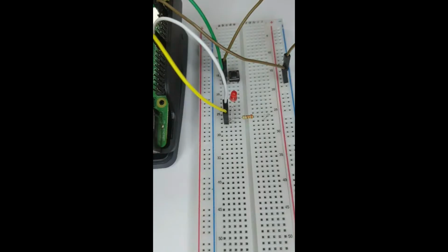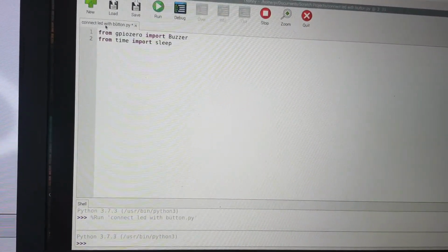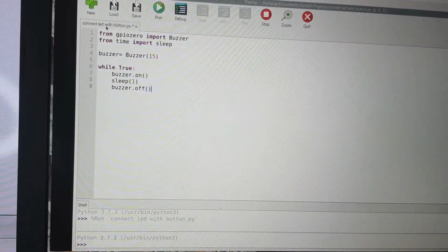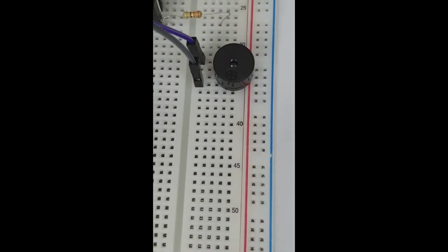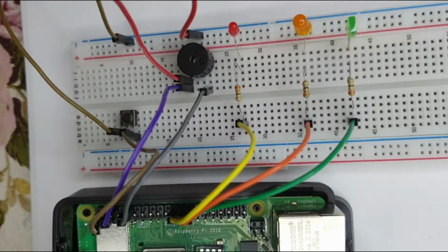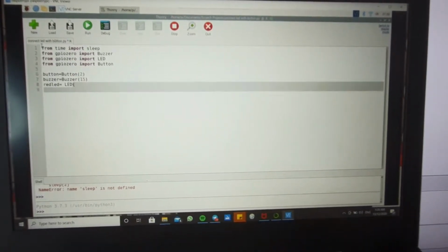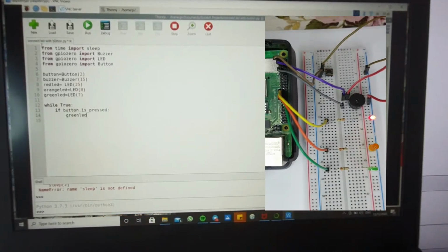To make a traffic light model, set up a buzzer, connect it to ground and GPIO 11. Write and execute this Python code and the buzzer will start to click in an interval of 0.5 seconds. Connect a yellow and green LED as shown here. Write out a Python code to simulate a traffic light sequence on 3 LEDs, push button, and buzzer.